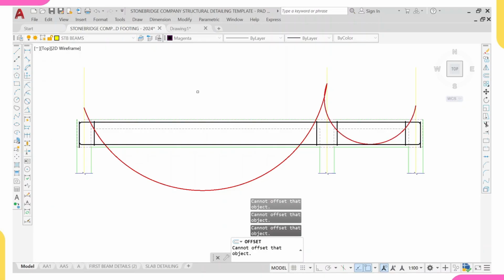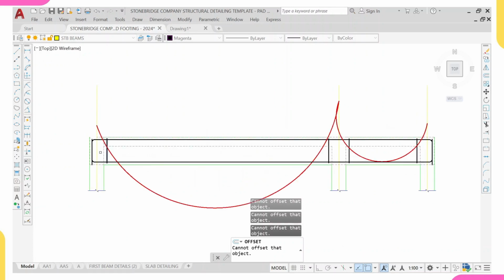Remember what we have said before, concrete is weak in tension. So that is why the bending moment diagram will always go like this. And for that reason, we will reinforce here. So that's why we do have bottom bars in slab, because our bending moment diagram will go like this, and we'll reinforce this.